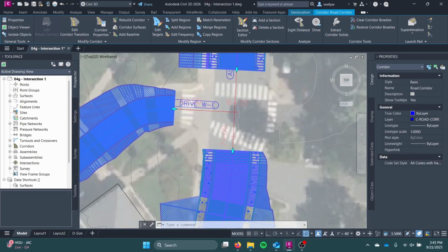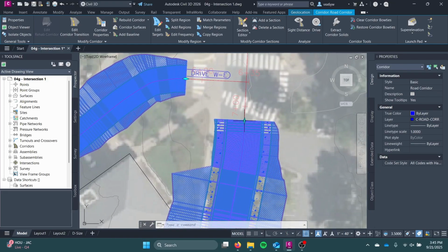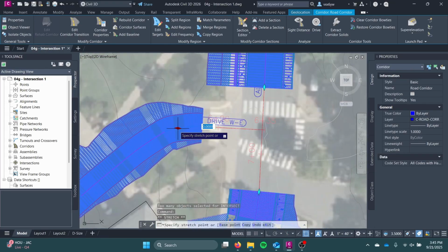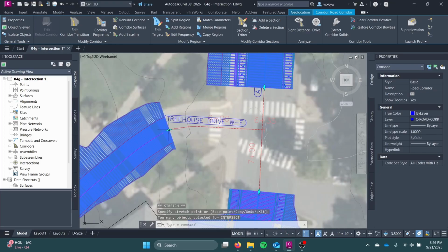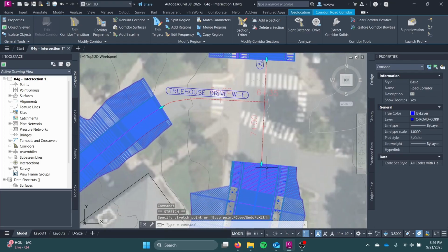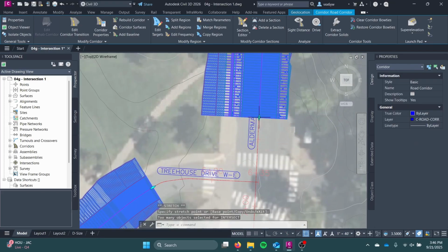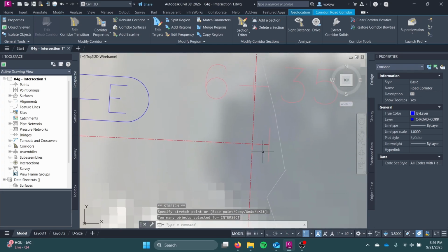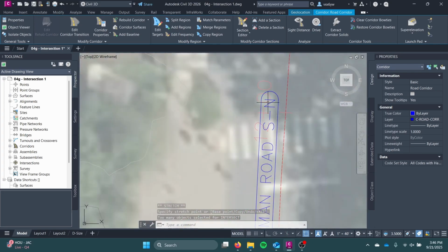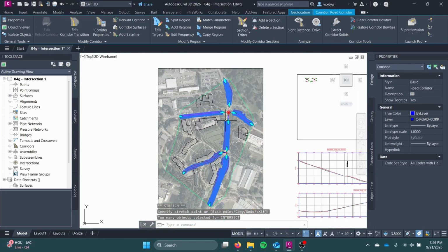So to start with the actual modeling, sorry that I talk a lot, I'm going to start by pulling back the existing corridor a couple more feet, give myself some space for the intersection. And we can always drag these back, and we definitely will. So I recommend dragging them out towards the further side. To create an intersection, you need to make sure that your alignments overlap. So for here, we have two alignments that overlap, and then here we have two alignments that overlap.